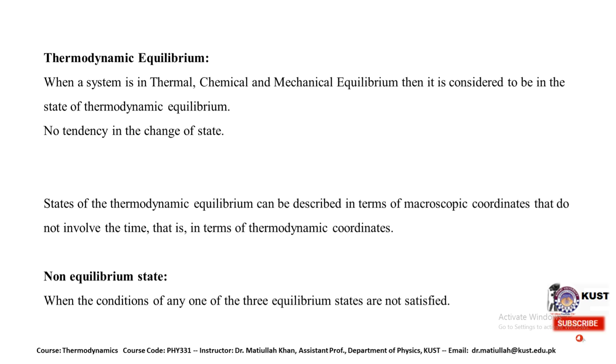of the system. So if we consider a system that is in thermodynamic equilibrium, there is no tendency for a change in the state of the system if it is not connected with other systems. I mean, if it is insulated from the surrounding. The state of thermodynamic equilibrium can be described in terms of macroscopic parameters that do not involve time, and it could be explained in terms of the thermodynamic coordinates. And the thermodynamic coordinates could be easily measured when the system is in thermodynamic equilibrium.